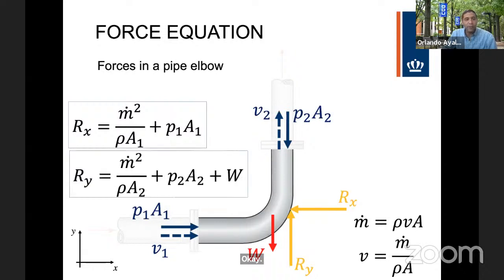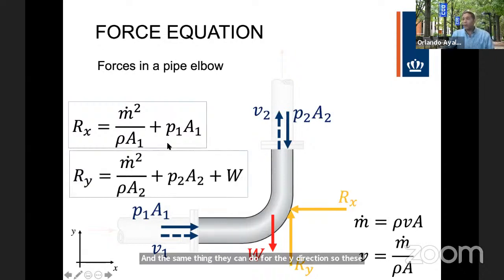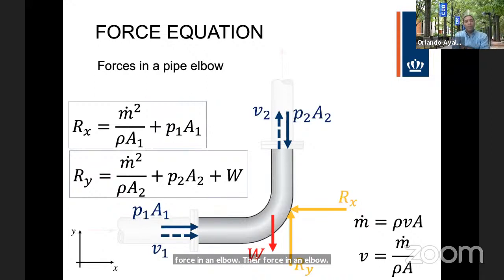And the same thing I can do for the Y direction. So these are the equations for the force in an elbow. Note that the force will increase with flow rate, and it will also increase with pressure.